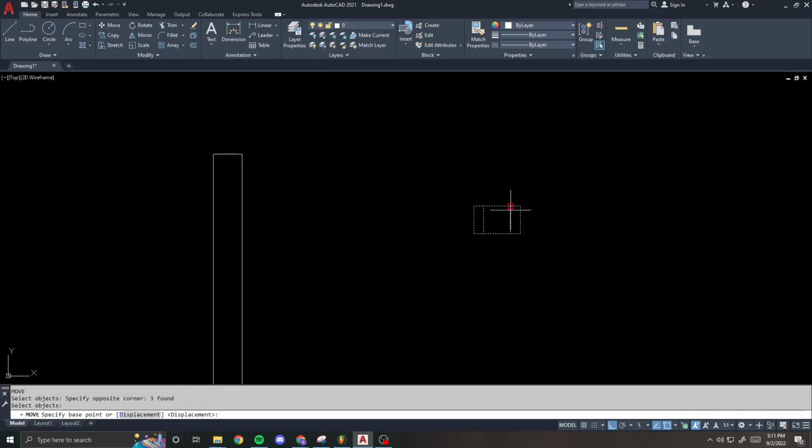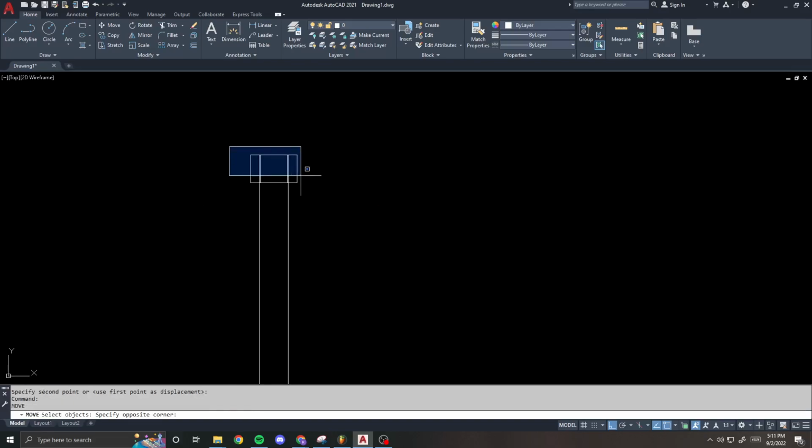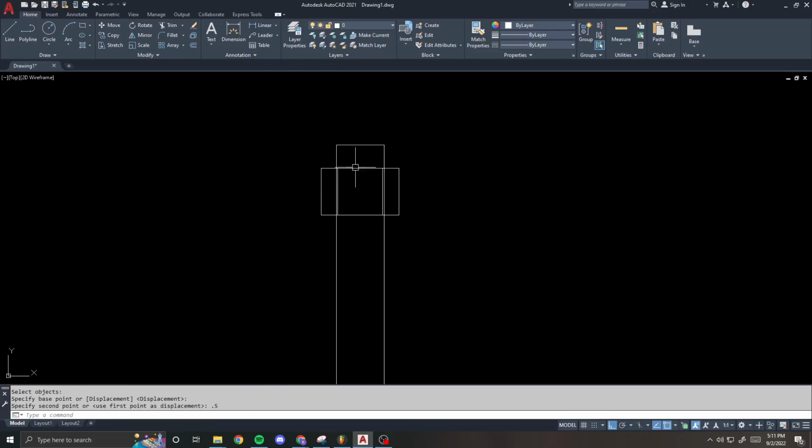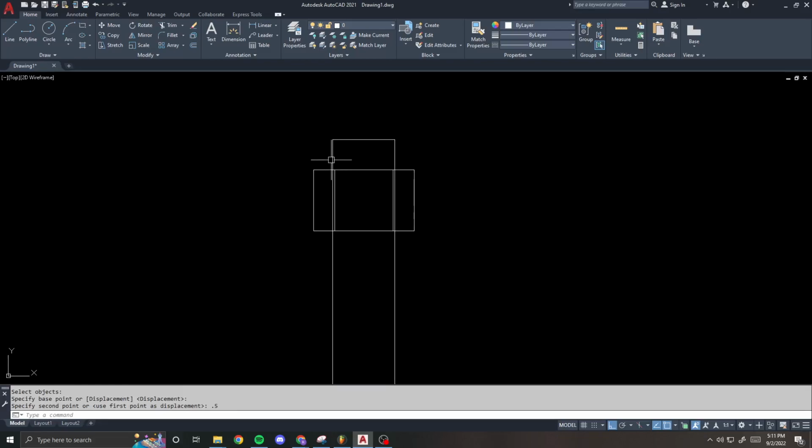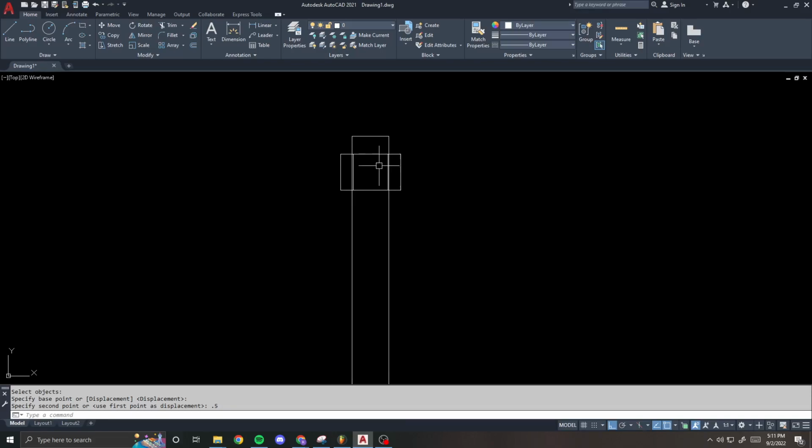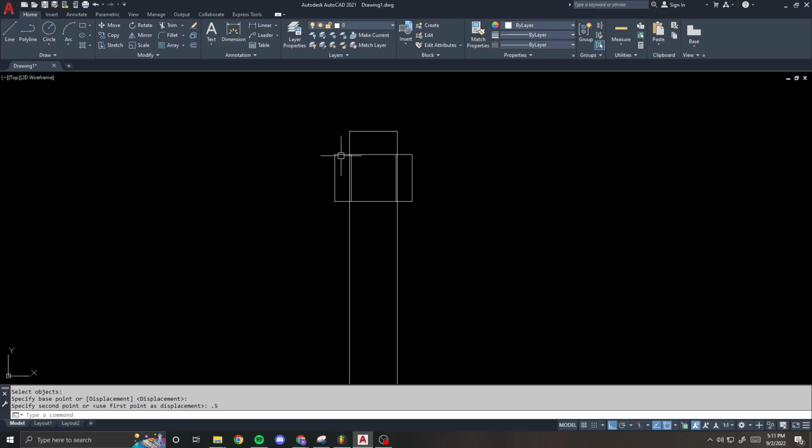All right, so I'm going to put my nut at the top, and then I'm going to bring it back down a 1/2 inch. The projection past the nut will differ depending on what your total projection of your bolt is, and the grip, like whatever the thickness of your materials is. There's a lot of factors going on here. But I usually give it 1/2 inch just to be safe.